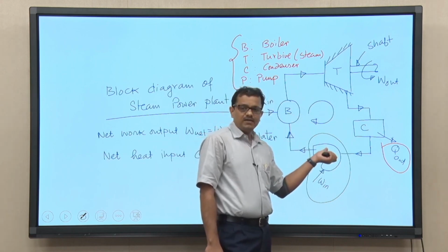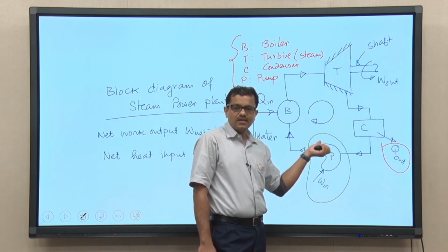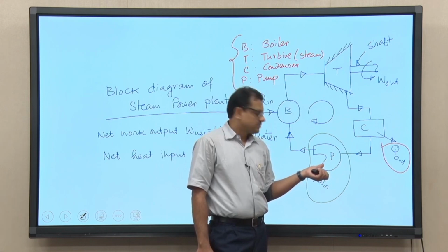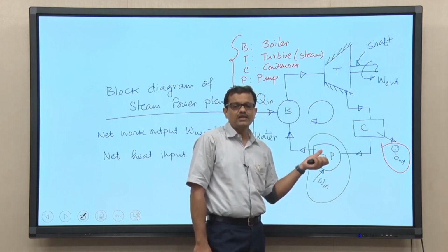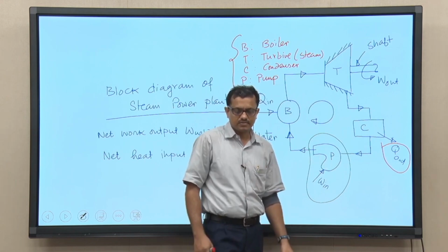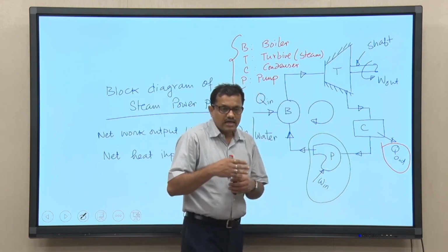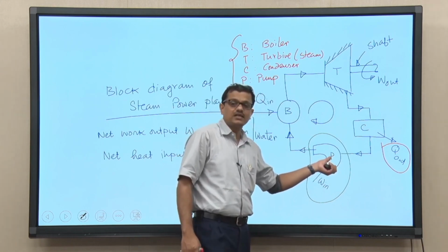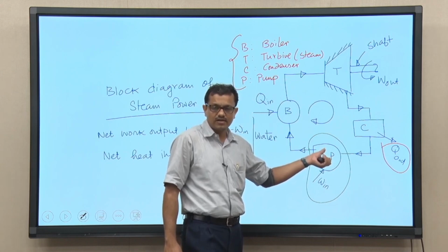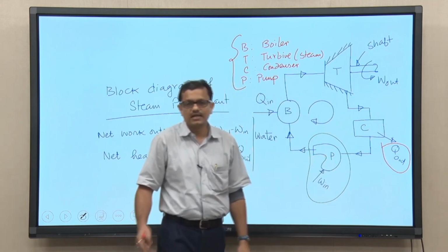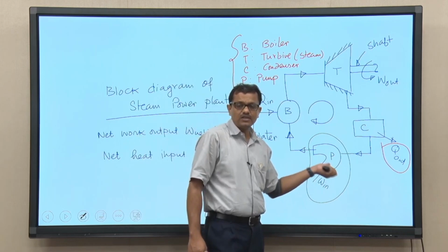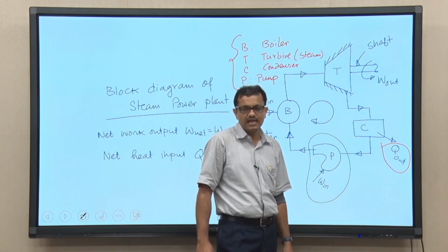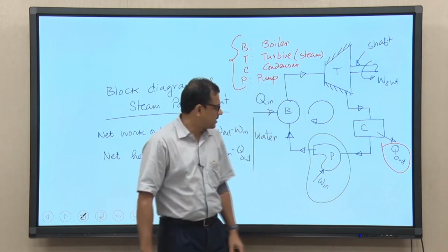While it is pumping, we need to identify whether the process is a reversible adiabatic process or a reversible isothermal process. By identifying the process, we will estimate the work needed, and it would be quite interesting to see that whether it is a reversible adiabatic process or reversible isothermal process is immaterial. The work done for both will be the same, and that we will do in the next class.